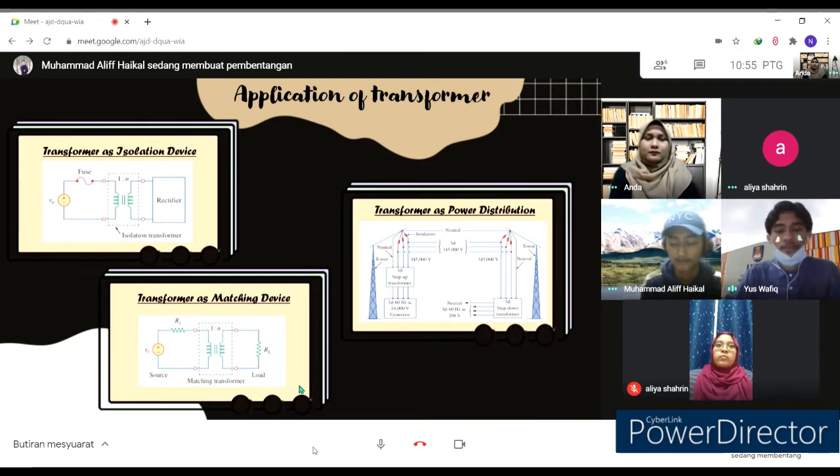Lastly, we have the transformer in power distribution. A distribution transformer or service transformer is a transformer that provides the final voltage transformation in the electric power distribution system, stepping down the voltage used in the distribution line to the level used by the consumer. As they usually don't operate at full load, they are designed to have maximum efficiency at lower loads. To have better efficiency, regulation in these transformers should be kept to a minimum. Hence, they are designed to have small leakage reactance. If mounted on a utility pole, they are also called pole mount transformers.